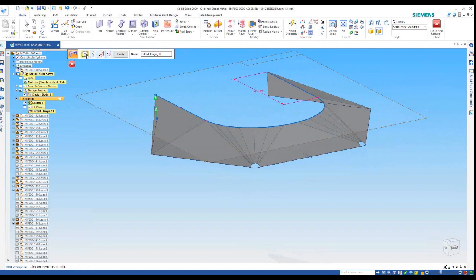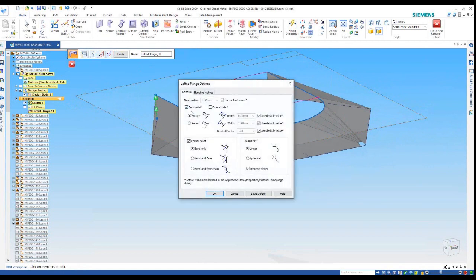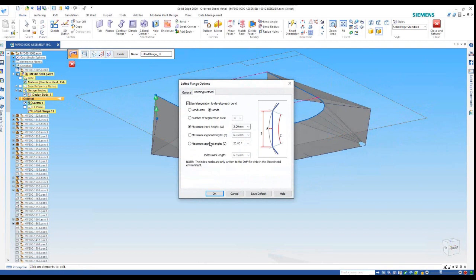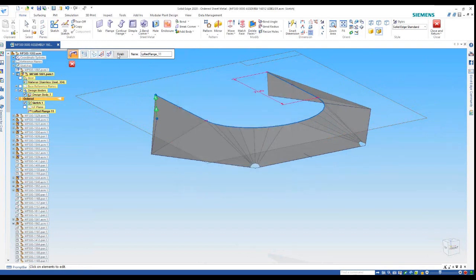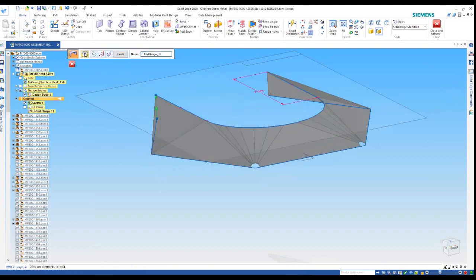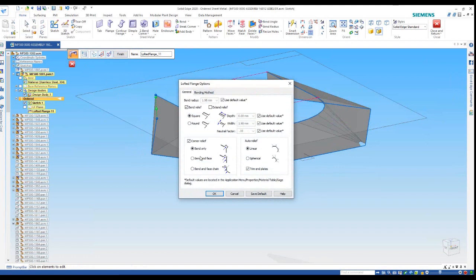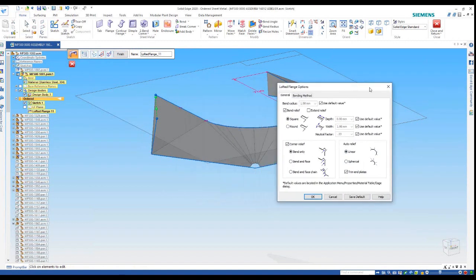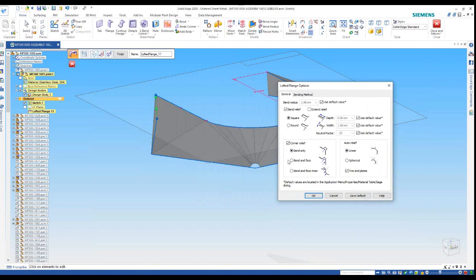And another option in Solid Edge sheet metal is, sorry, it's not there. Where is it? To do with these bend relief. Oh, here it is, sorry, missed it. Typically, you have auto relief options around these bends where they are nested closely together.